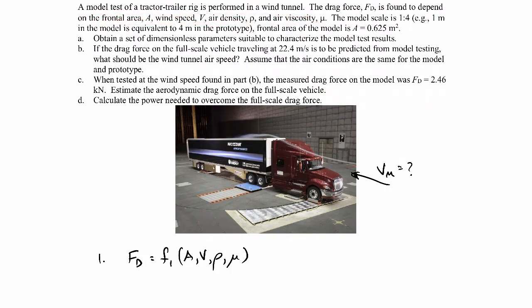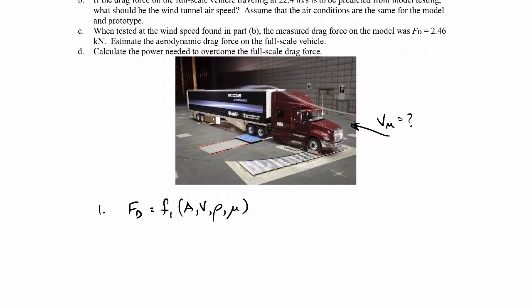That's often the hardest part of any dimensional analysis problem, figuring out what variables are the significant ones. You only get that through experience and practice, and occasionally through trial and error, maybe some preliminary experiments. It can be very difficult to get that relationship, but we're giving it to you here, so that's good. Okay, step 2 in the dimensional analysis is to write out what the basic dimensions are for each of the variables that we had in step 1.